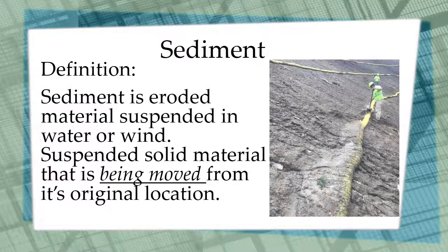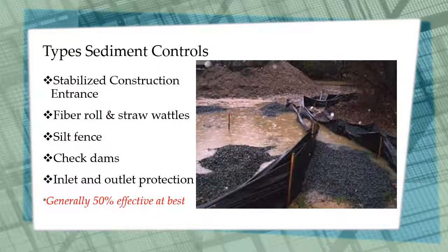Make sure you understand the difference between erosion and sediment, as there will be a test question about this at the end. Sediment control BMPs include stabilizing your construction entrance, fiber rolls and straw wattles, silt fence, check dams, and inlet and outlet protection.